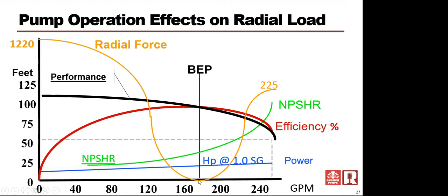At best efficiency point, there's very little radial force. That pump is running very smooth. There's not a lot of side force one way or another on that impeller. Therefore, the bearings and the shafting and all that stuff are running extremely smooth in that pump.